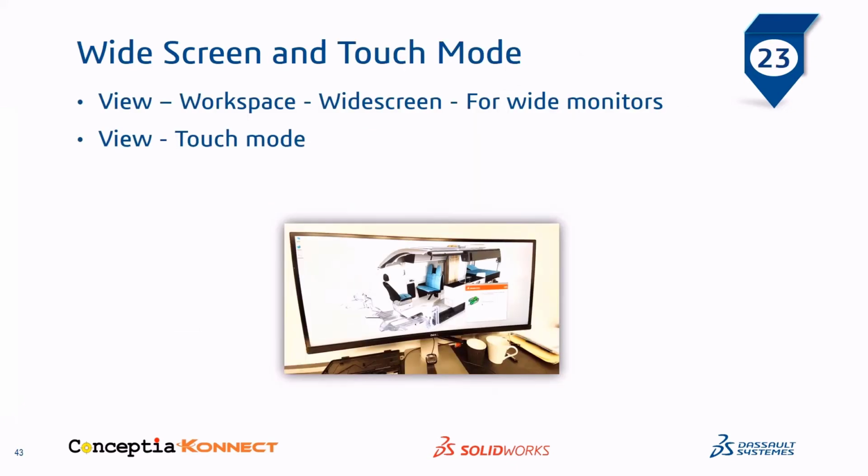Number 23. Widescreen and touch mode. If you are using touch devices and dual or wide monitors, enable them and use them as they should be used. Go to View, Workspace, Widescreen for wide monitors, or View, Touch mode for touch devices.